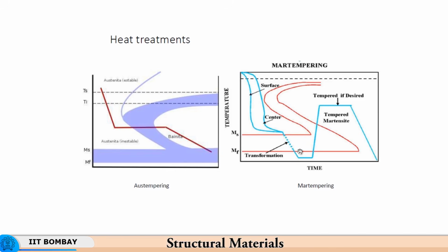Now you have come to martensite finish over here. Now again, if you want martensite to be hard, you can leave it at that, but normally what happens is as hardness increases, toughness goes down. So now you want martensite to be both hard as well as tough. So that is why what you do is you heat it again. Okay, you heat it again to a temperature which is well below the austenitizing temperature. So you heat it to a temperature where it will form some amount of pearlite. So you reduce the amount of carbon in the martensite.